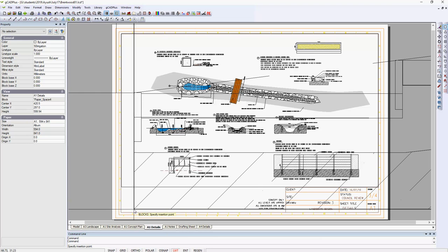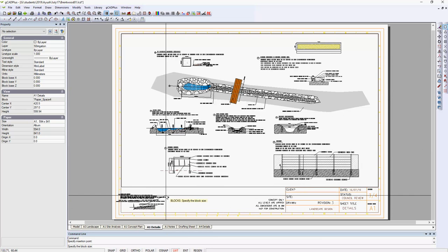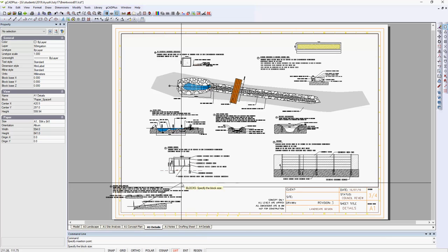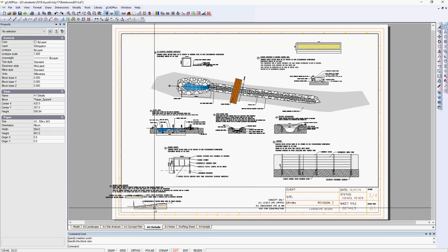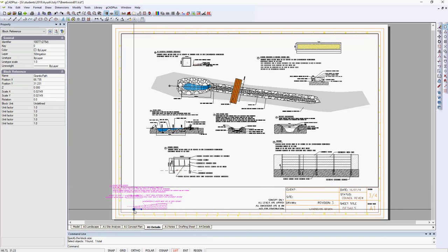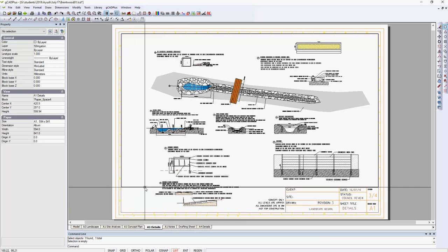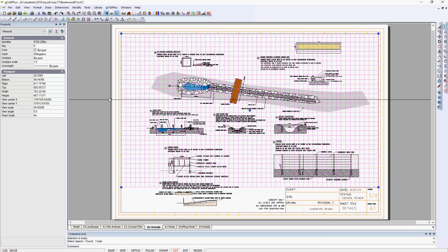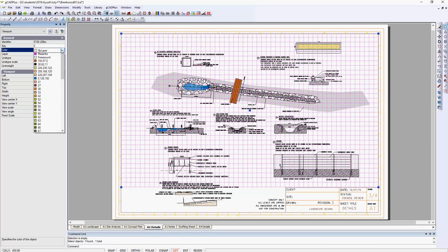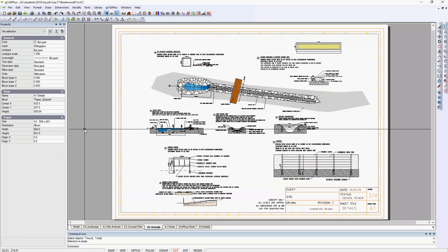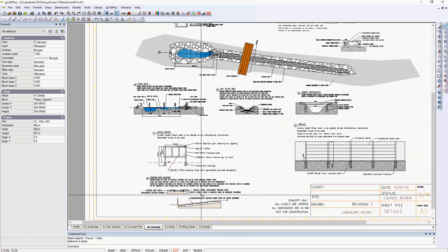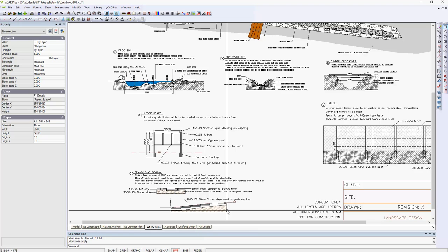We'd like to sit it down here. Notice how big it is, but as we drag up like so, we can just dynamically adjust the appearance of the detail to suit. And then if I take that floating viewport now and set its color to 255, essentially it disappears. So the detail that we lifted from one drawing is now being used in another drawing.